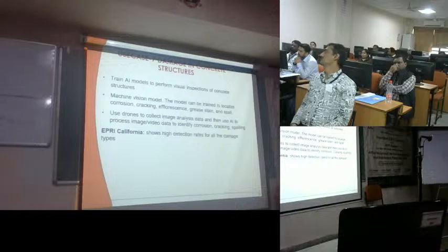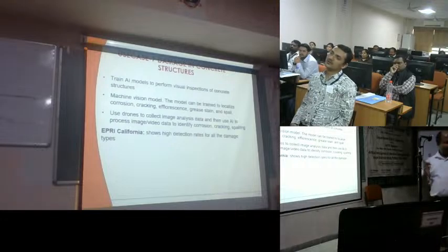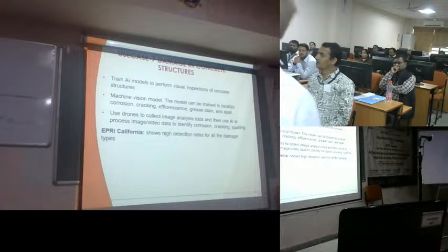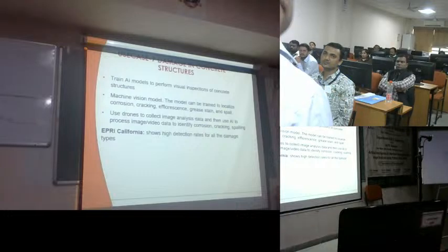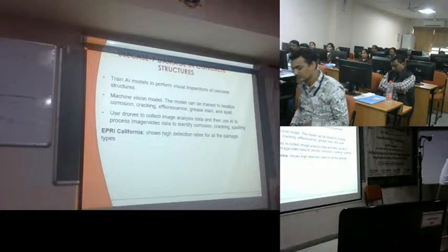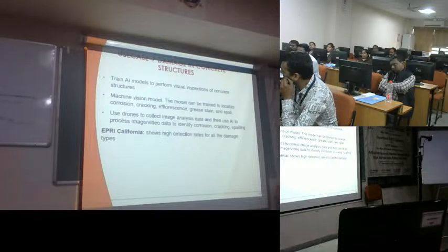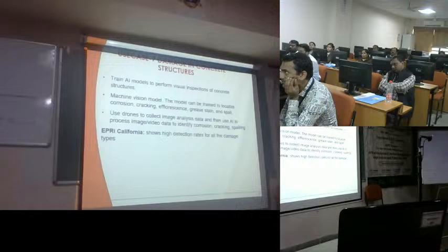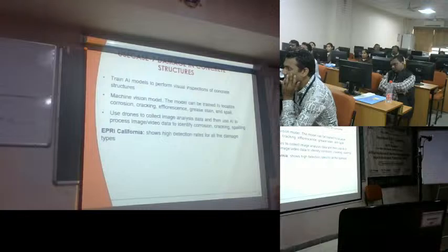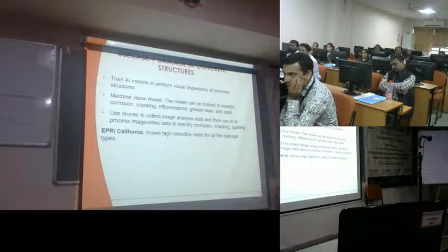In this way, I can ensure that no radioactivity is released from this area. These are civil technologies, but we can easily identify damage in the structure. Like metallic corrosion, which has a pattern in the manner in which it propagates, damage in the concrete structure also has a systematic way of degrading, which will be analyzed from the pictures taken.